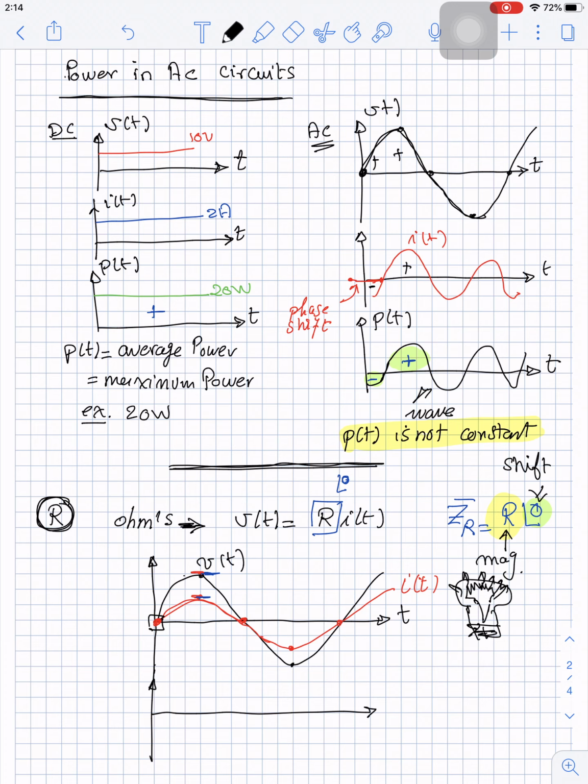When I is positive here, V is also positive. So when you multiply V and I, you get positive power, or consumed energy. When the voltage reverses and becomes negative, at the same instant the current reverses, so the product is still positive. You still consume energy. This element physically cannot regenerate or store energy. We said the passive element on average will take energy.